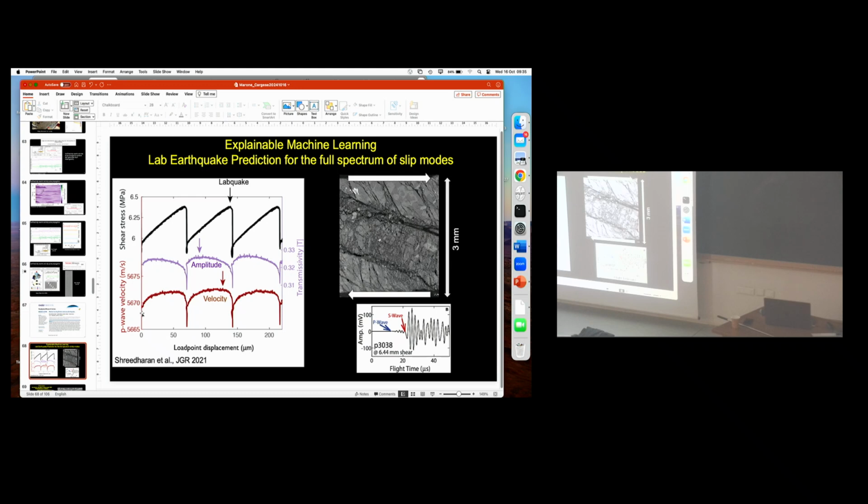In those experiments, if you just go at a constant velocity, you end up seeing one characteristic set of events, depending upon the normal stress. And as you accumulate strain, you see some variations in it. But especially in those, the wear rate is so low that you don't have a strong change in K sub c as a function of strain. But we are imposing velocity changes to try to understand what happened then. So I think maybe the answer is that, yeah, we're just imposing them.